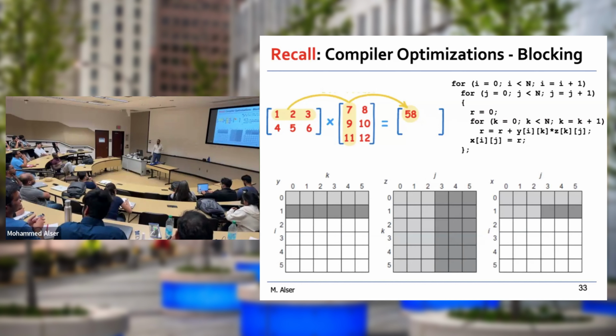For example, instead of accessing one column at a time, meaning that for every row I need to access the entire row from DRAM, access the entire row, bring only the first column, move to the next row, bring the first column, and so on, instead of doing that, I could go for a larger number of columns. So you access the first row, but bring like 5 columns, for example. Now it's much better than bringing only the first column.